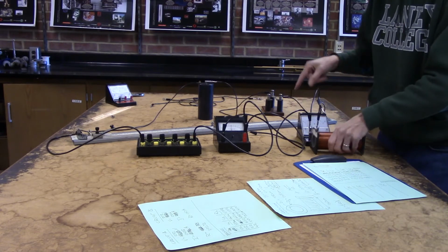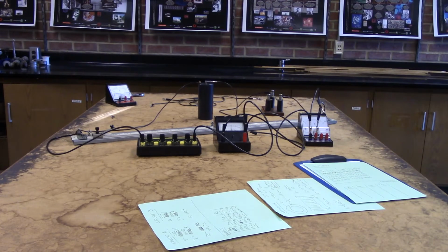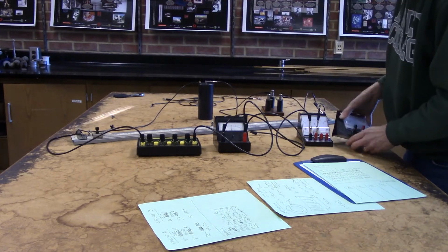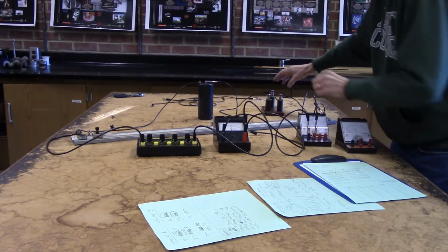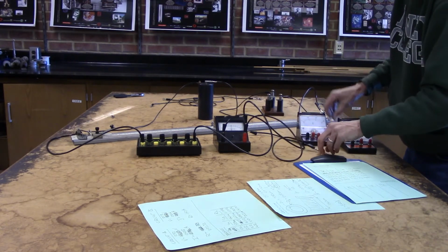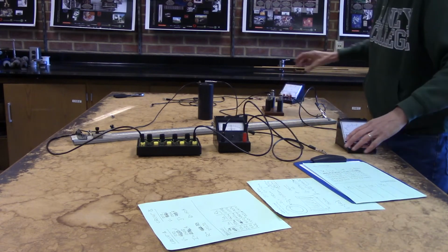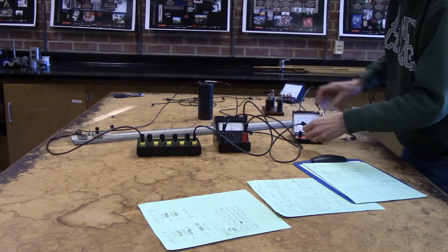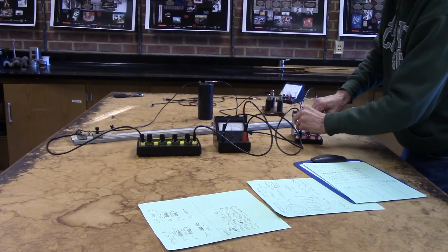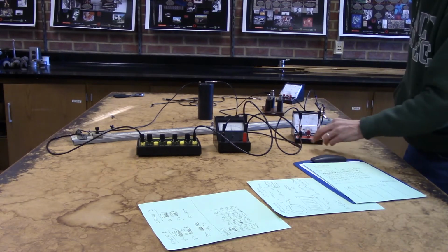But let me do that. Let me switch out the voltmeter, and I'm going to bring in the ammeter. So here goes the voltmeter. I'm going to turn the circuit off, give the battery a bit of a break, and take out the voltmeter. Now for the ammeter, I think I'm going to set it at the highest reading. I'm guessing that that's where the resistance will be the highest.